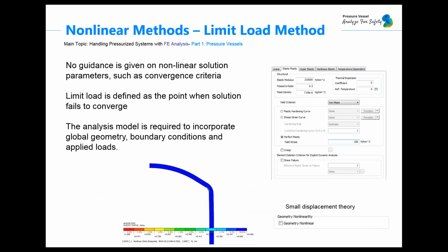And this has been presented in the right picture on the past slide actually. At this moment we see an example of limit stress analysis. The analysis has been performed inside FEA software. What is important is that there is no good guidance in the code, and the code doesn't say anything about convergence criteria.